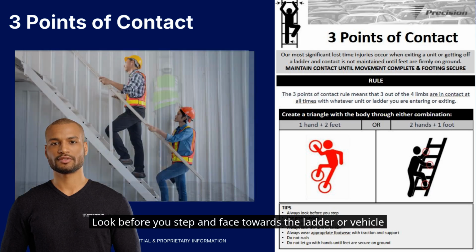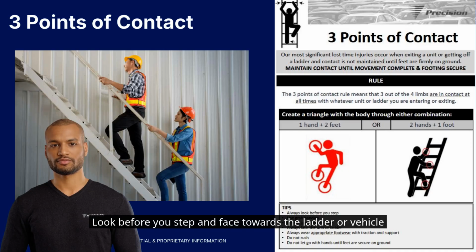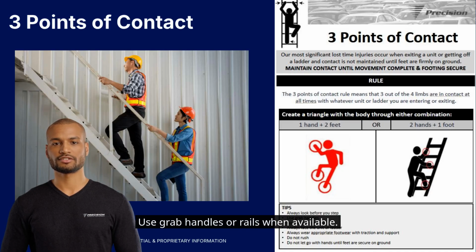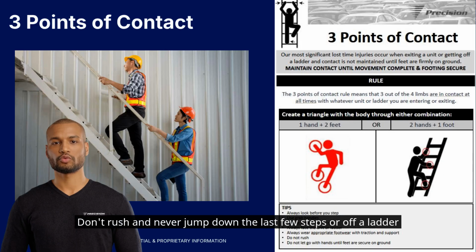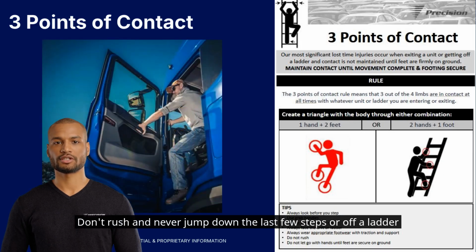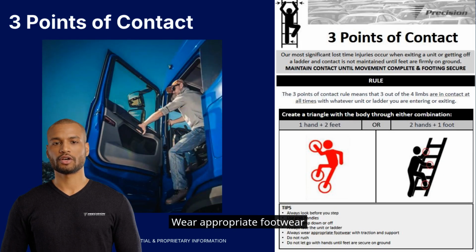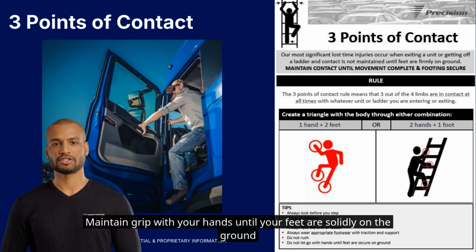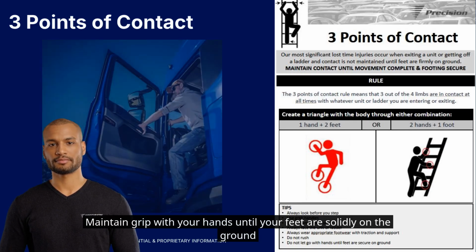Look before you step and face towards the ladder or vehicle. Use grab handles or rails when available. Don't rush and never jump down the last few steps or off a ladder. Wear appropriate footwear. Maintain grip with your hands until your feet are solidly on the ground.